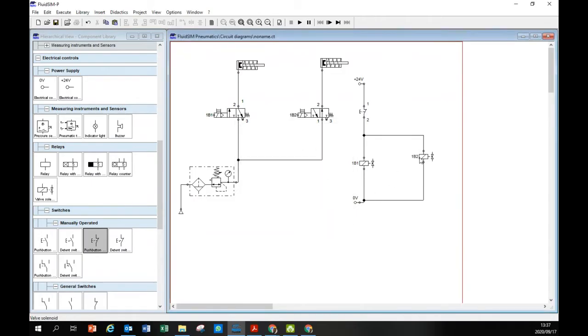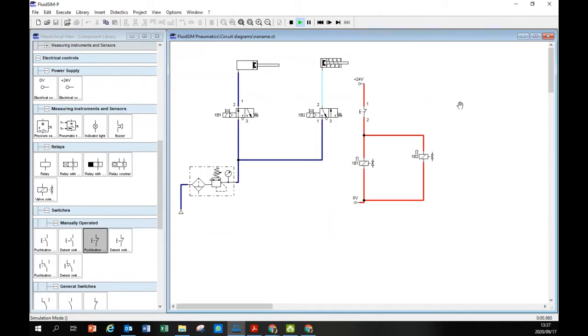Okay? And then mechanical. Observe. What's happening now? Look at this one. When it gets electricity, it gets closed. Air goes in. It gets open. Air goes in. This one, the air, it closes. It was open, it closes. Remember, you need to respect the normal state. That's why they say normally open, normally closed. So next time when they ask what's the state, you start by stating whether it's normally open or normally closed.